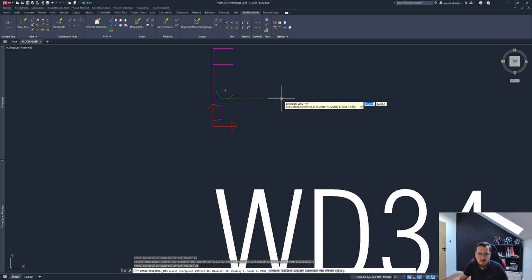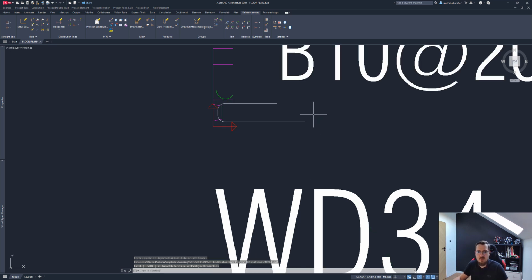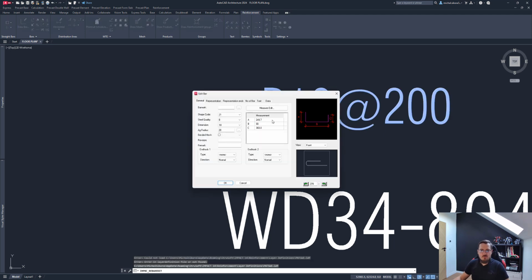What I'll do is I'll just go like this, like this, like this, and like this. Oops, undo. Like this, and space. The size really doesn't matter at this stage. What I need to do is edit this bar. And with that, I will manually update the size. Let's say 400 here, 400 here, which will be perfect, and 80 for this particular width of the bar. And that's it. What I also do is delete the text, which we don't need.